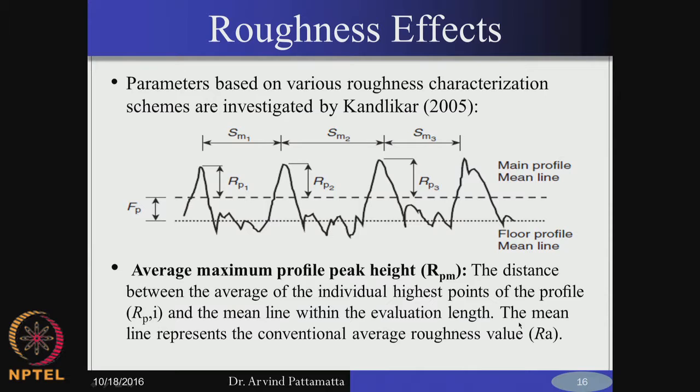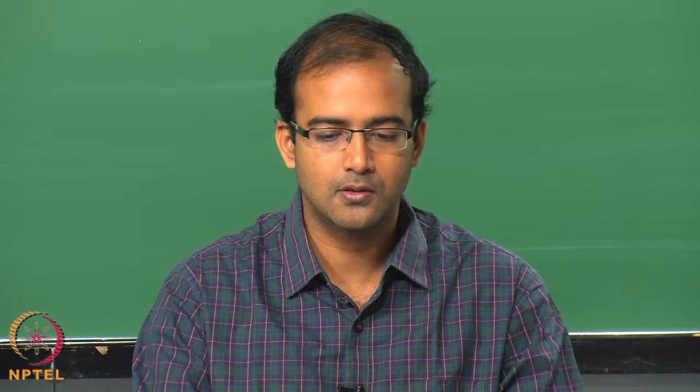All the previous discussion is valid only for perfectly smooth channels, no roughness. So you use the same correlations for the friction factor as the macro channel, same Poiseuille number and so on. But in any practical micro channel, if you look at the surface profile, it is not smooth and definitely has considerable roughness, and the roughness to diameter ratio, which is very important, will be quite significant in micro channels. The roughness itself will be of the order of a few microns compared to the channel diameter of the order of a few hundred microns. So in the year 2005, Kandlikar